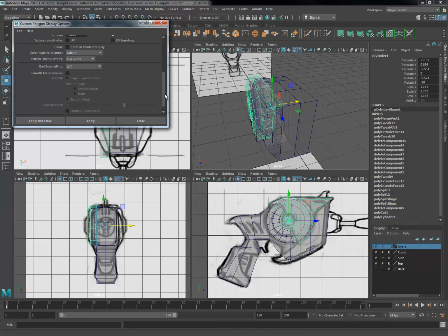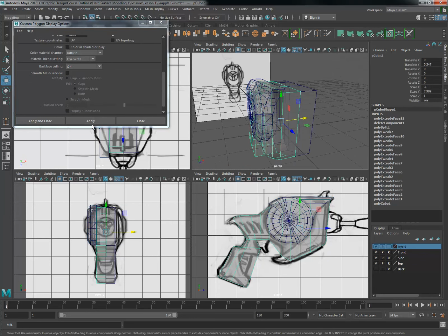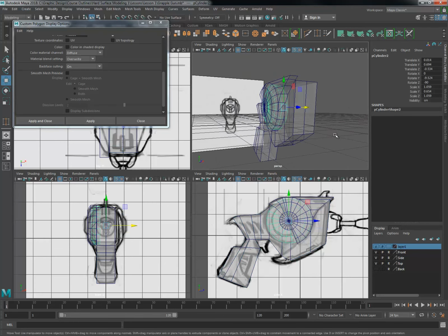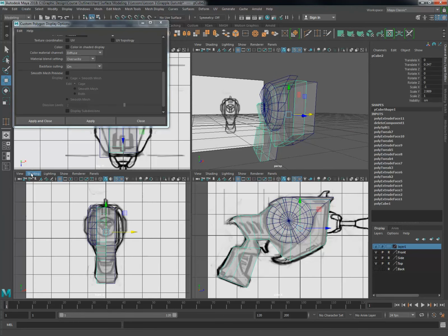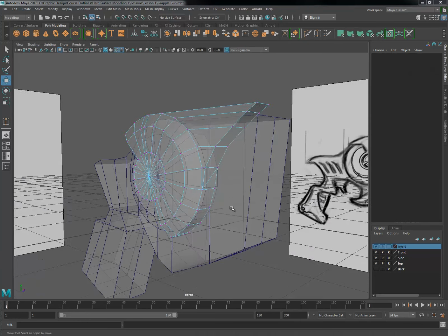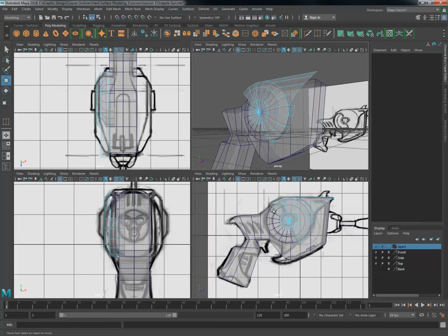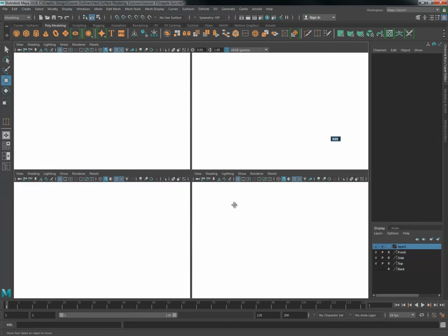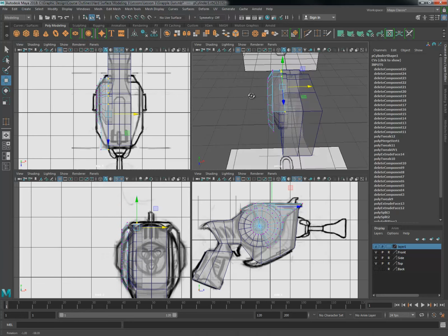So it just seems to work best to take these more complicated round forms and use them as the priority and extrude the geometry that you're going to use that's going to be connected to them. Just extrude that right out from them, and then connect that geometry to your other geometry, to the rest of your base.